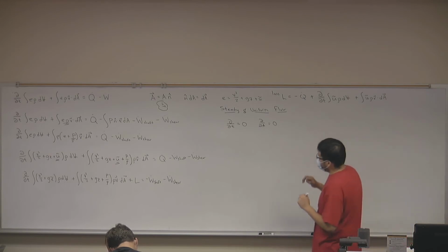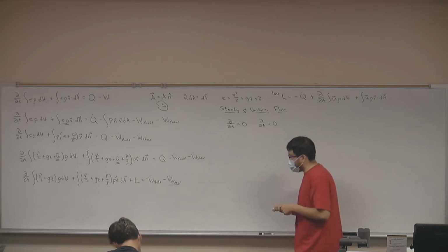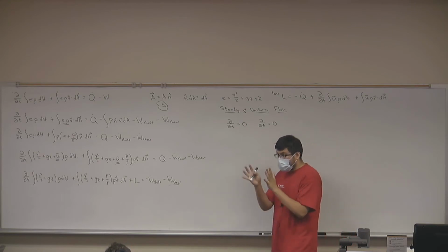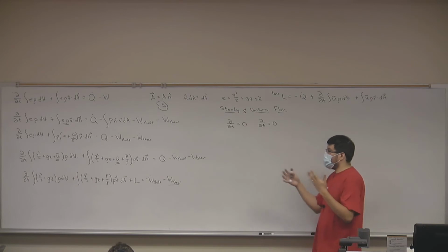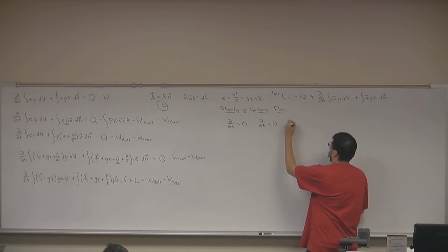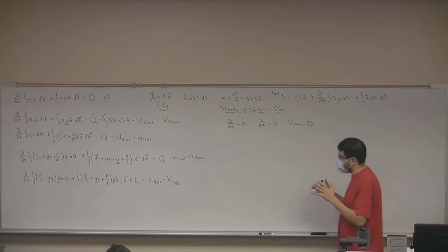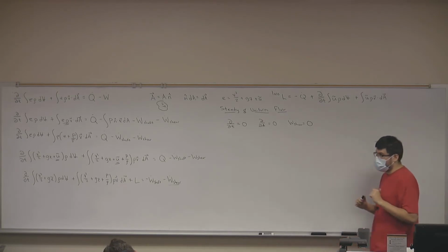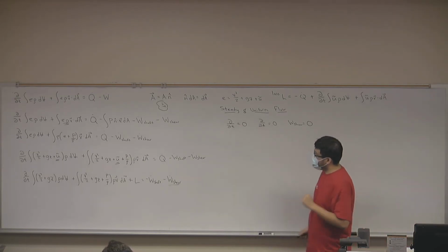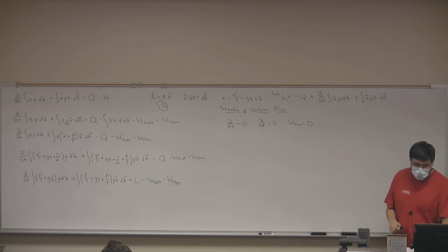Now, if my flow is steady and uniform, the shear work, that is the work that occurs from the movement of your control volume, should be 0, because if my flow is steady, then my control volume should not move. My control volume cannot move if I'm calling it a steady flow. So for steady uniform flows, we will pretty much neglect any shear stress, because we will focus on stationary control volumes. And now what does the equation look like? Because I think that if I apply these two assumptions, steady and uniform flow, this equation is going to take a much more manageable form.